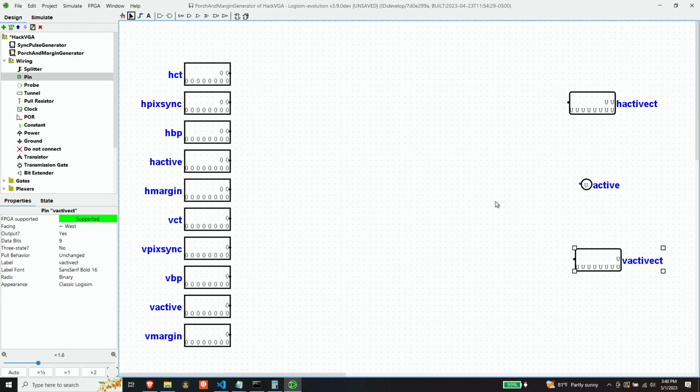I'm just going to write a way to shoot out various test patterns to the display to just prove that everything is sort of working. But when this component becomes integrated into the Hack computer, we're going to need to know what row and column the display is asking for, so that we can fetch that from memory and return it. And so that's what these two are going to be used for later.